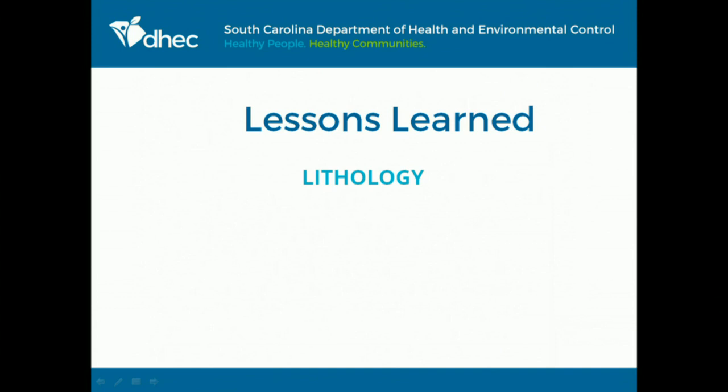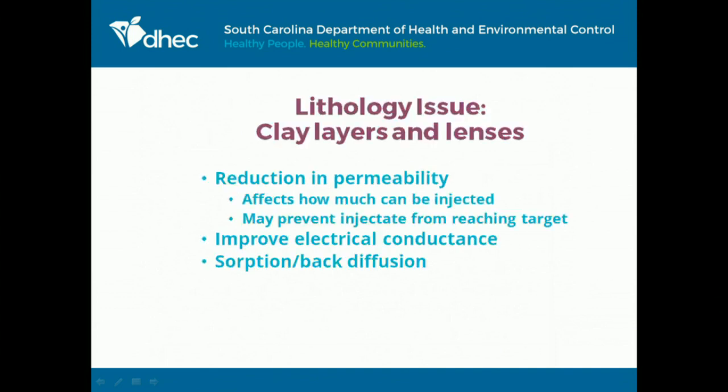So the next group of lessons learned when I looked at innovative technologies in South Carolina was lithology. It plays a key role in the success or failure of some of these technologies. Clay layers and lenses, very common across South Carolina. They reduce permeability. They can affect how much you can inject in the subsurface, and they can prevent the injectate from reaching the subsurface. They can improve the electrical conductance, which is a good thing if you're looking at a thermal technology.